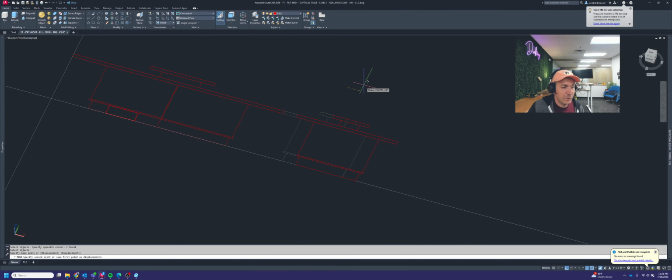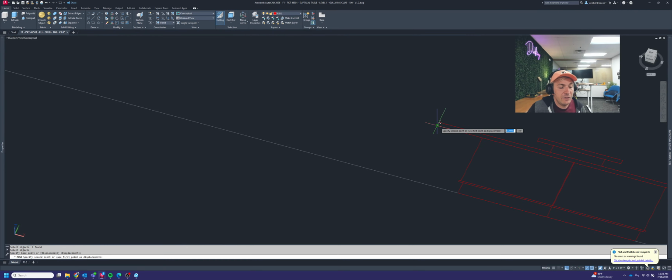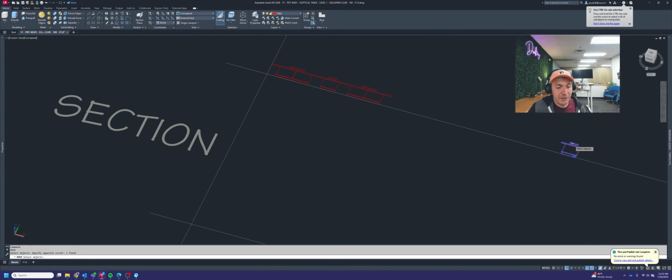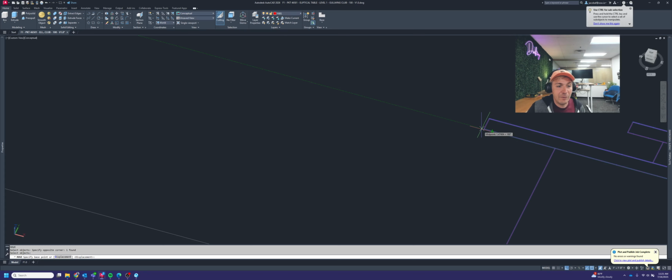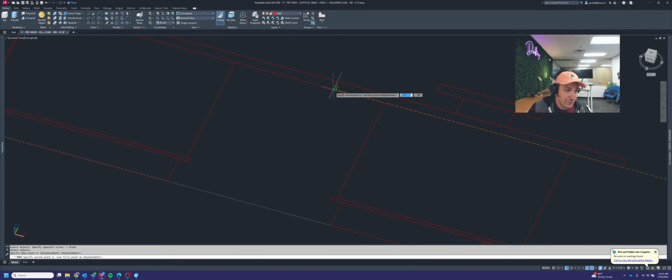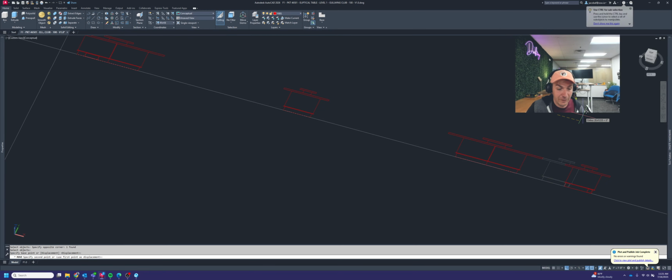And when I have multiple views for each category, like in this case, the elevation view has 4 views, what I like to do is space them either 150 inches or 300 inches away from one another. That way, when I'm putting dimensions or adding material calls or hardware calls to my views, there's a lot of extra margin room in between these views. If I start with 150 and that looks sufficient, then I'm going to keep that as a standard for this print. And 150 definitely seems like it's going to be perfect for this.